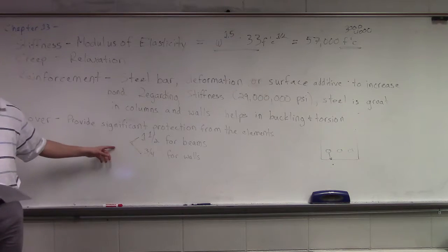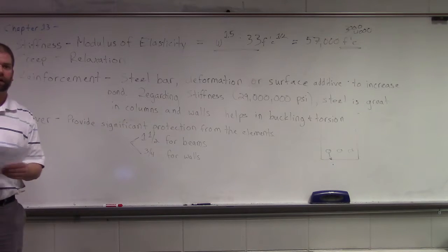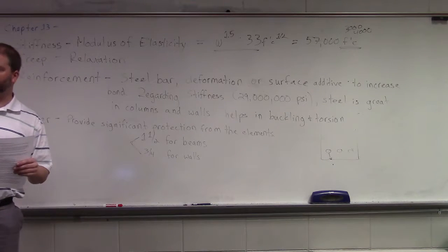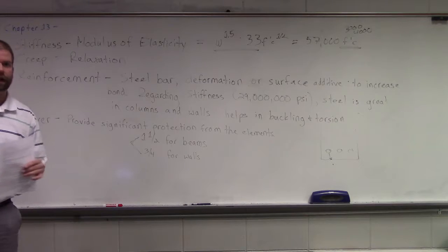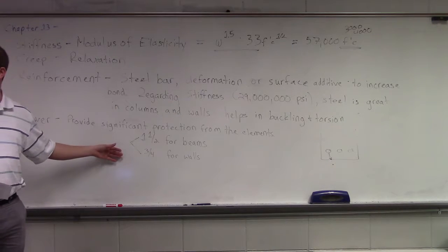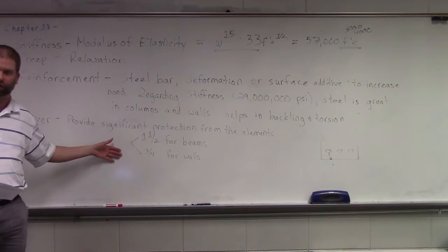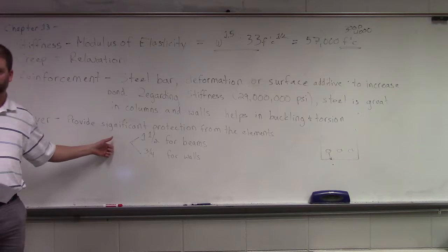From the life cycle, we do need to be aware of, and you can see it on bridges throughout the country, that it gets to a point where this cover will start degrading. Once it starts degrading, we begin having exposed steel.